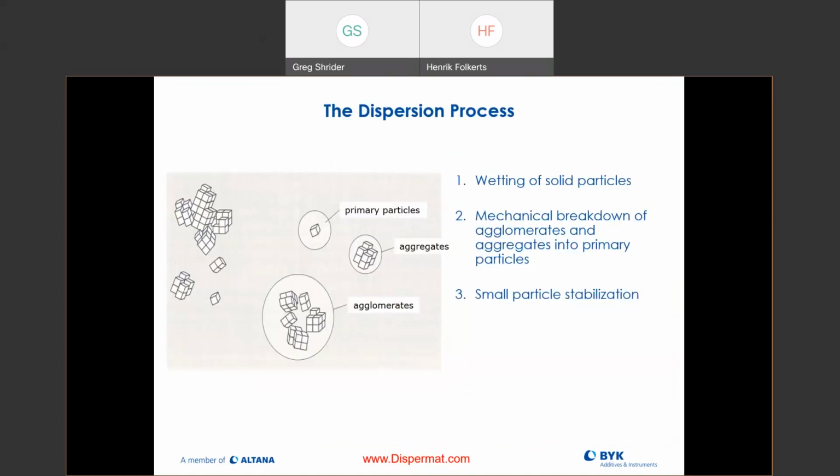So the dispersion process, first of all, we have these clusters of our pigments. We call these larger clusters agglomerates, as you can see in the slide right there. And then the next smaller cluster, once we break up these binding forces with our high-speed Cowles blade, with the high tip speed, we're able to rip them up and then turn these larger agglomerate clusters into smaller particle clusters.